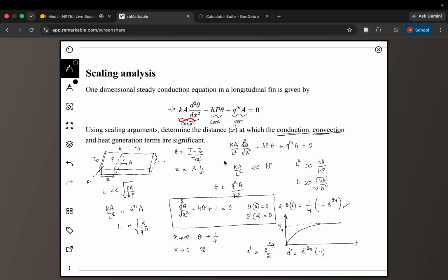That is our boundary layer region, and beyond a particular point, the second order derivative will become small enough so that the other terms will balance each other. That is, the inertia and the pressure forces will balance each other, where your Euler equation will apply. That is in the outer region. So in a boundary layer, you'll have two different regions. There will be an inner region where you'll have the second order derivative becoming important. So that is our boundary layer region.